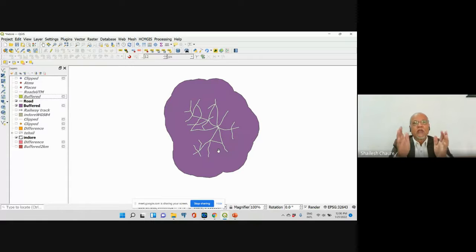That is why we have the UTM projection maps. In that, you divide the entire globe into certain rectangular zones, and you set the origin at the left bottom of that rectangular zone. With reference to that, you calculate the coordinates within that area. So you assume that that particular part of Earth is flat. Whatever you calculate, you don't have to do any complex trigonometry, because the curvature of Earth is not being taken into consideration there. That is why for calculation purposes, it is better to go to the appropriate UTM zone to which your area belongs.